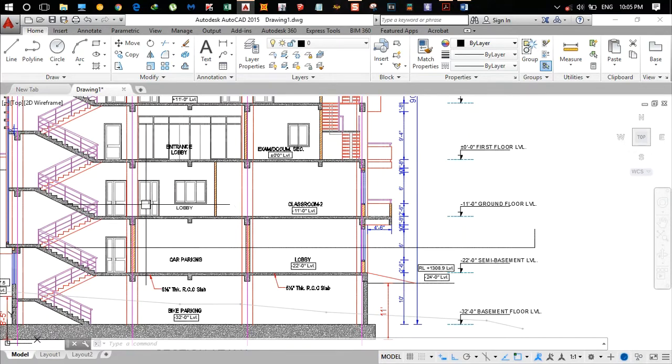So we got some weight here, half weight here, half weight here. So we add these two. For example, if the weight is A here, weight is B here, we do A plus B. If it is C, we lump or concentrate that weight in this floor. So that weight is the seismic weight of ground floor.